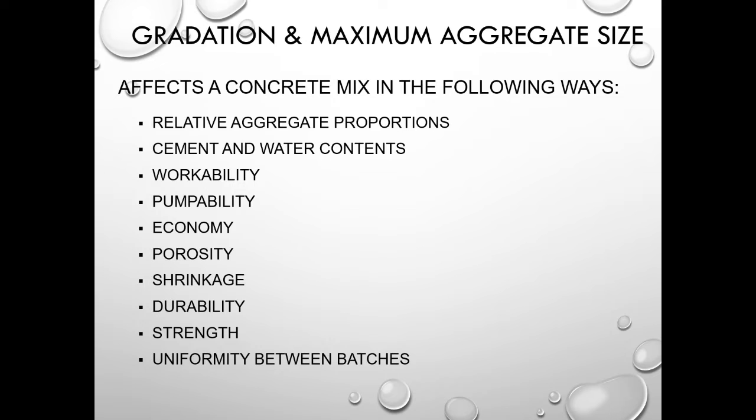Shrinkage. We know that concrete is initially fluid when we first mix it, and then as it sets up and cures, it becomes a solid. So anything that dries usually shrinks. Okay, volume change. The grading of the aggregate has a very big bearing on how much it is going to shrink. The finer the grading, the more the concrete's going to shrink. For a simple reason, the finer the aggregate, the more water we need to make it work. So again, we'll look at that when we're doing concrete mix designs.